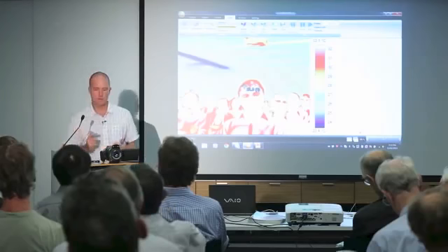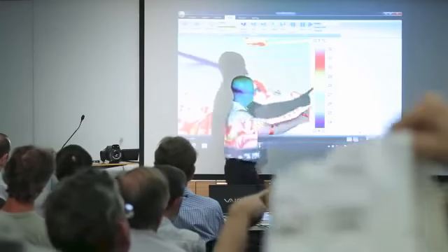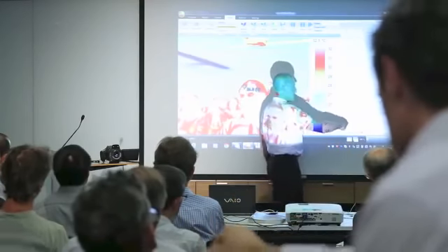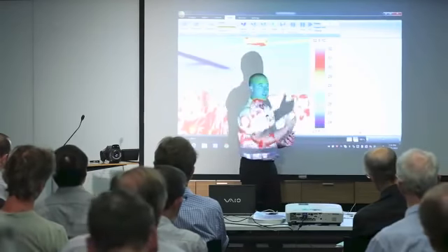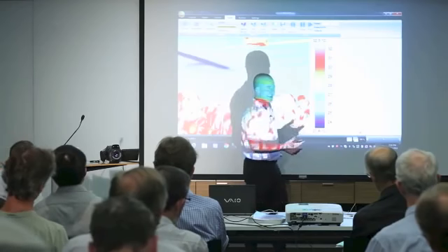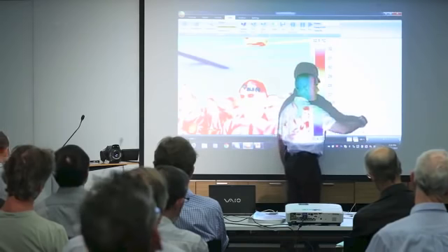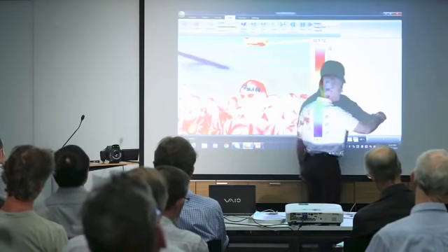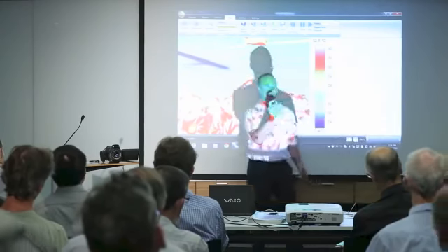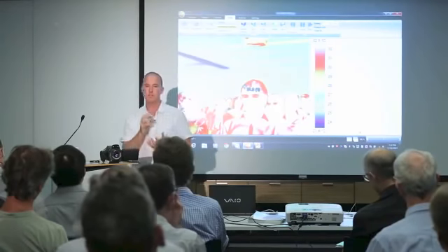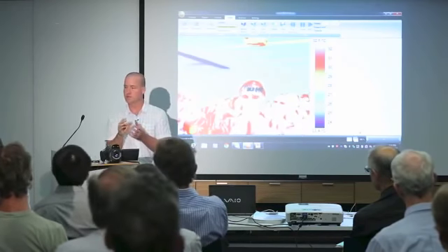If you look at the phase change, I don't have a whiteboard here, but I'll pretend I've got a whiteboard. It's my whiteboard finger. If you take normal water and you heat it, it gets hot. Everyone agree with that? Sensible heat absorption: you put heat in, it gets hot, it makes sense. Latent heat absorption: you take ice and you heat it, and what happens to it? It doesn't get hot. Eventually it melts to a liquid, then it goes up again, then it hits 100, and what happens? Flatlines again. That's latent heat. It's when you're putting heat in and it's not actually getting hot because it's using all the energy to change the structure of the material. So your question is, isn't water a phase change material while it's liquid?